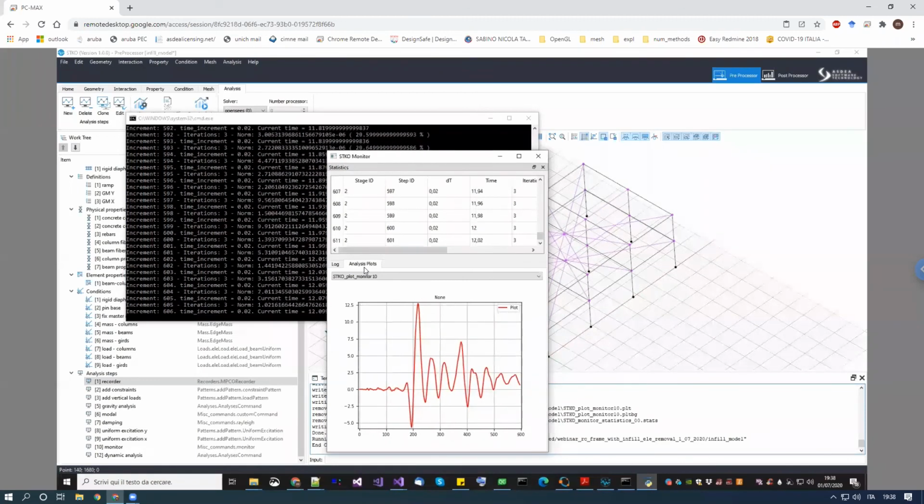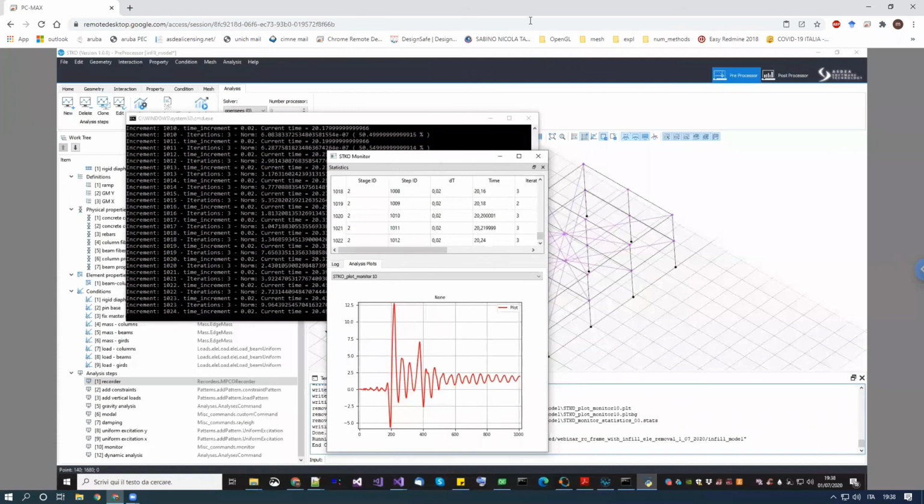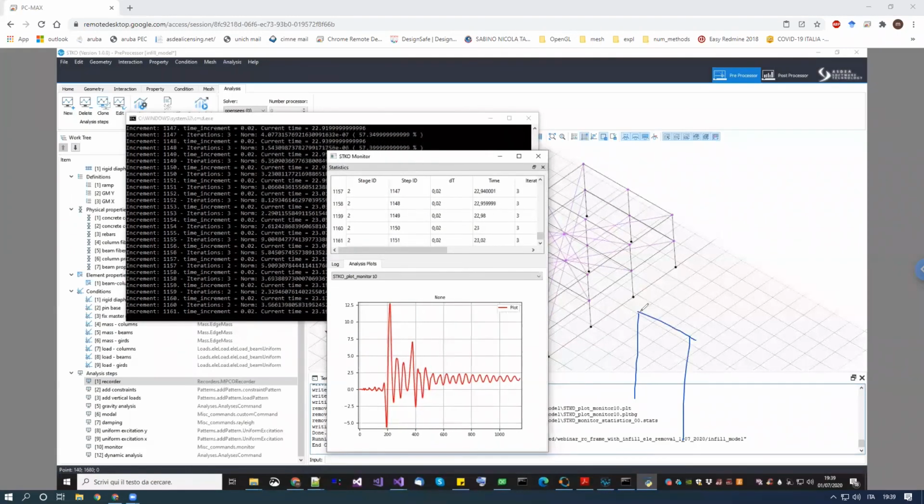So for example, if you want to model a cavity wall, a wall with a cavity, if you model that cavity just with a single shell using different layers of material, for example, our brick, and then inside you put a void material, for example, that material is like a rigid material in the sense that the two layers cannot create a shear deformation like this. Let me give you a brief example. I can use the annotation. Now imagine this one is my shell in 3D, okay?